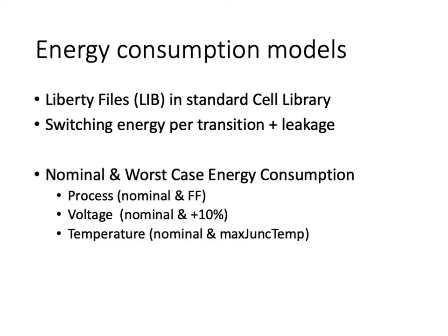So in this lesson, we will talk about how to estimate the leakage power, as well as the short circuit crowbar current power, which is associated with switching and dynamic activity. Okay, the steps for converting an RTL, Verilog or VHDL design into a final circuit level representation netlist that can be estimated are as follows.